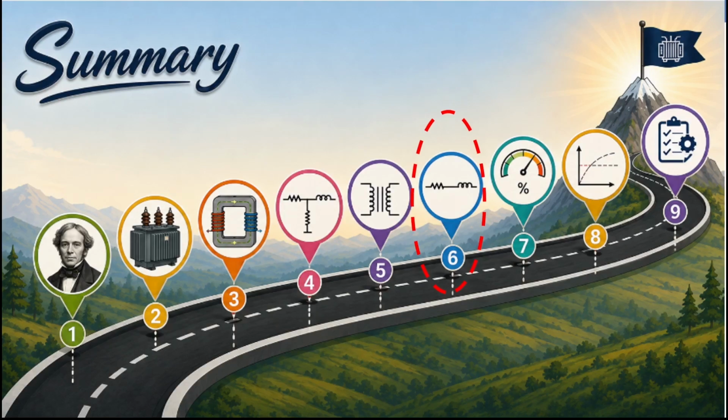After establishing the equivalent circuit, we investigated the transformer performance by studying efficiency and voltage regulation, and we saw how these quantities help us to evaluate the quality of the transformer under different loading conditions. Finally, in the last part of the course, we learned how engineers determine the equivalent circuit parameters through standard transformer tests, completing the link between theoretical analysis and practical engineering.